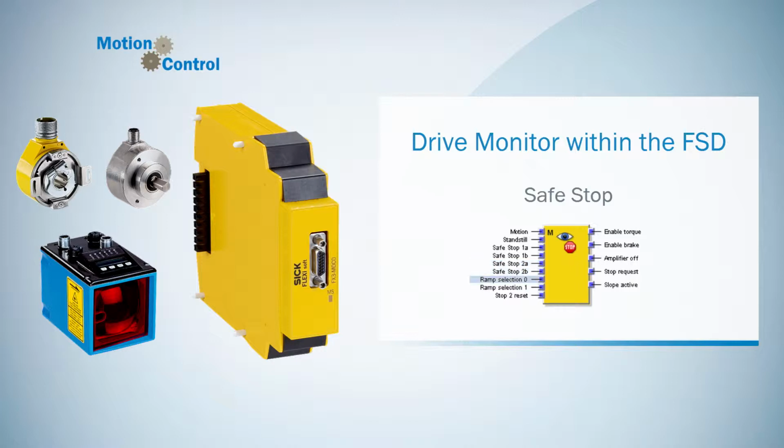The inputs RampSelection0 and RampSelection1 are used to select between up to 4 configurable stop ramps. Last but not least, there's the input Stop2Reset, with which a saveStop2 can be reset by a rising edge after a standstill has been detected.